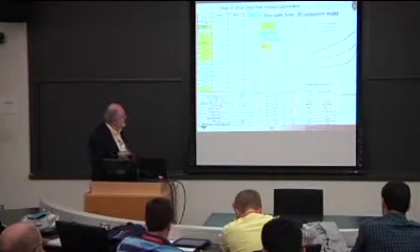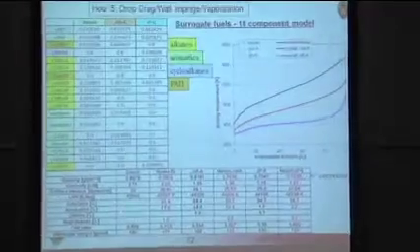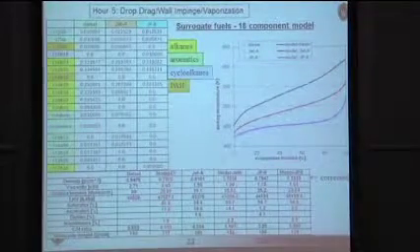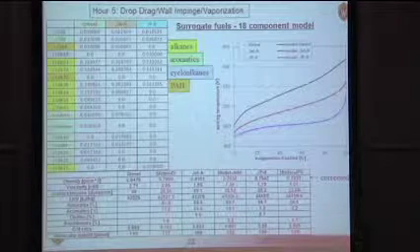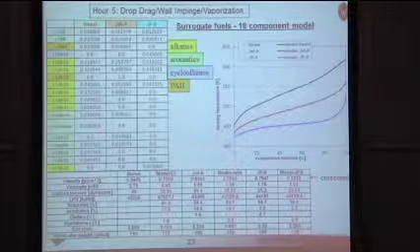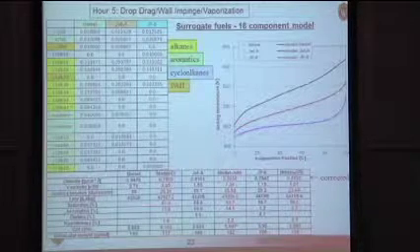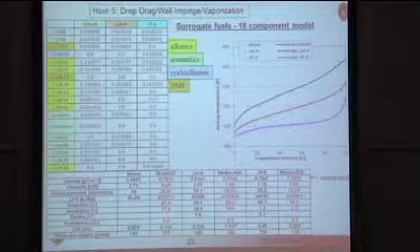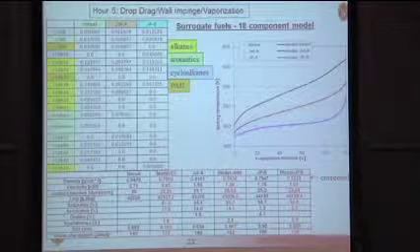Of course, we're interested in more than just the distillation curve. We're also interested in density, viscosity, surface tension, lower heating value, the amount of saturates in the mixture, the amount of aromatics, olefins, naphthalene, C/H ratio, molecular weight. And so for these particular surrogates that you see here, you see a comparison between measured and modeled. Most of the results look reasonable.